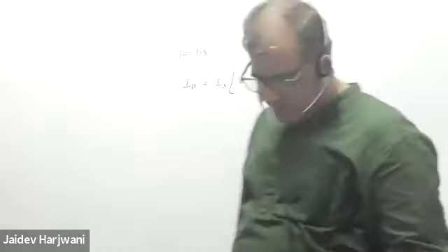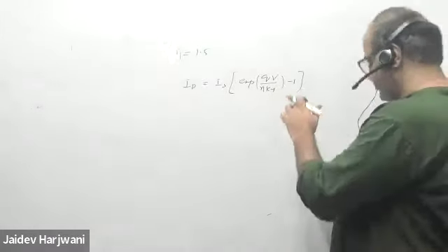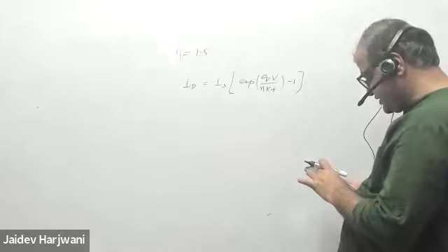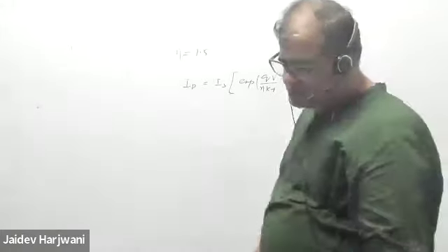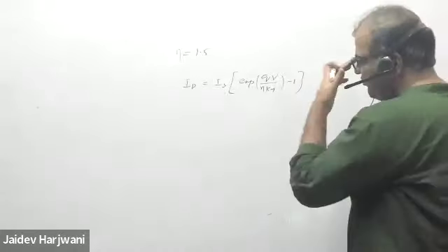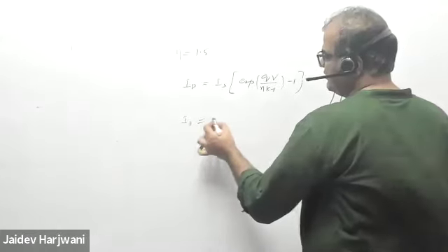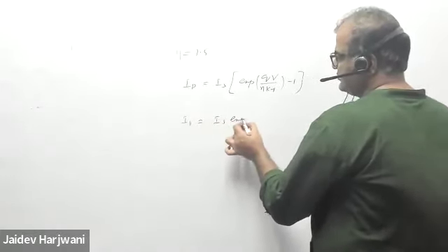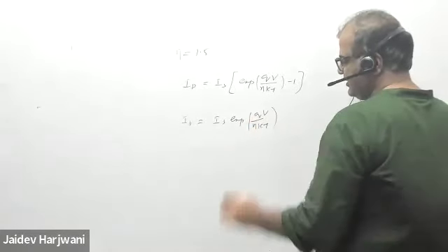And now what is given in the question? You have to find the voltage if current changes from 0.1 milliampere to 10 milliampere. So we assume this is forward bias because current is given in milliampere. So I can say ID equal to IS exponential QV upon eta KT.